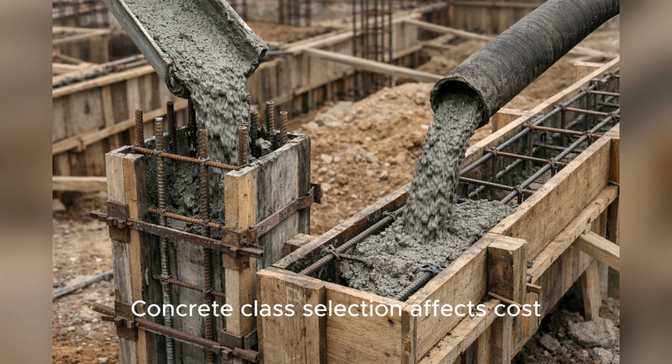Concrete class selection affects cost. Structural columns and tie beams typically require higher strength concrete compared to non-structural elements. DPWH unit cost includes labor for placement and vibration, equipment for mixing or pumping, and materials for cement and aggregates.